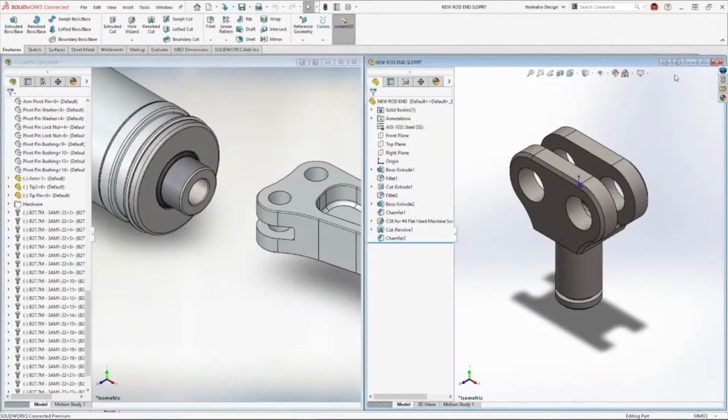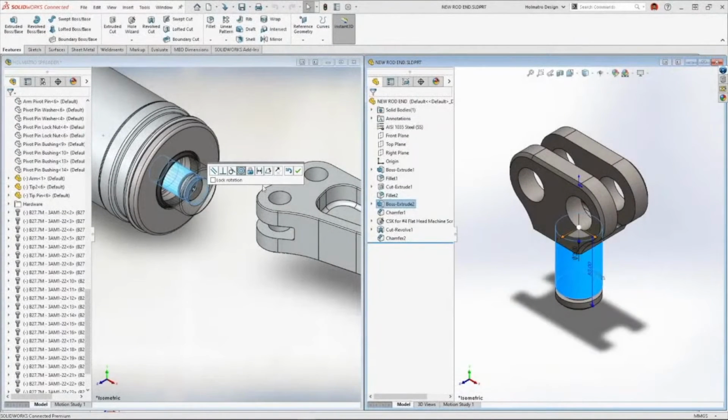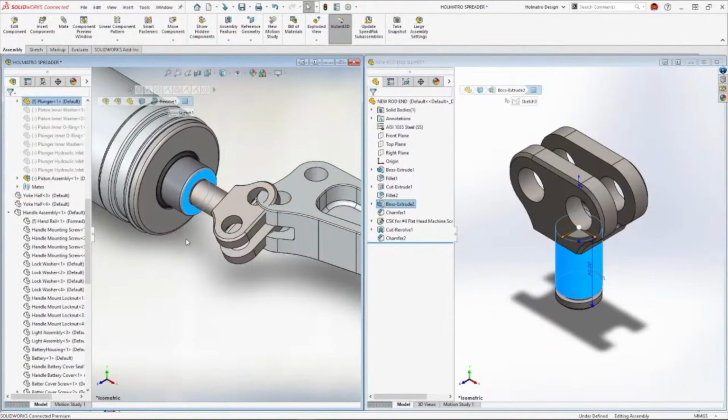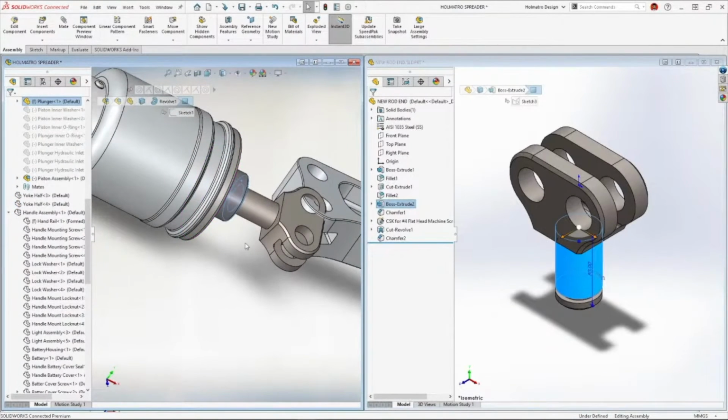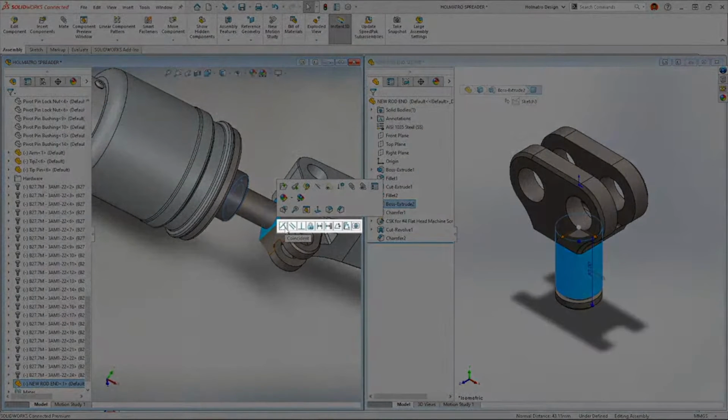He's going to toggle into the window and watch as he drags and drops this into the assembly. I mean, that's pretty cool. It automatically adds a concentric mate. And obviously this isn't the right direction, so, well, it's no issue. It just flips the mate around and press the green check. So, I mean, adding mates is just super simple. So if you wanted these two faces to touch, just select the two faces and add a coincident mate.